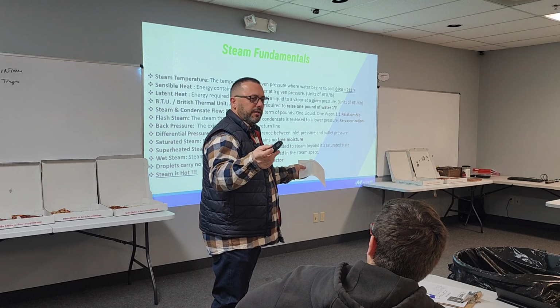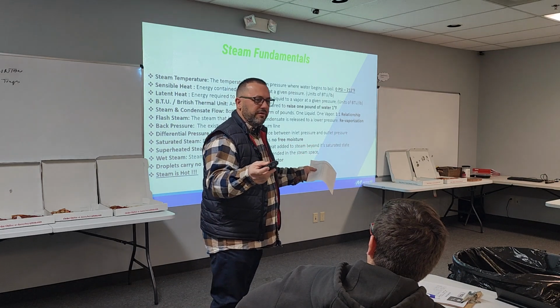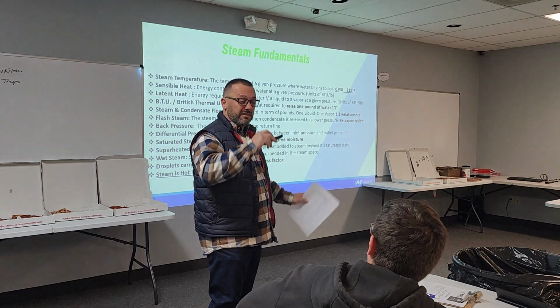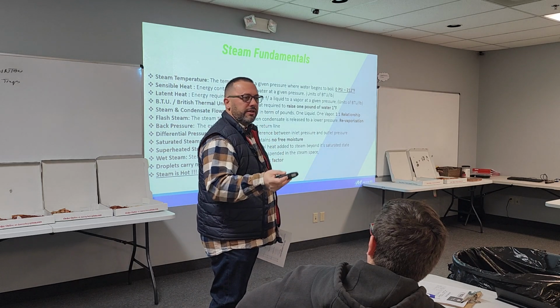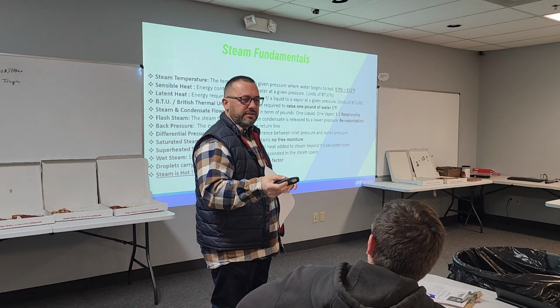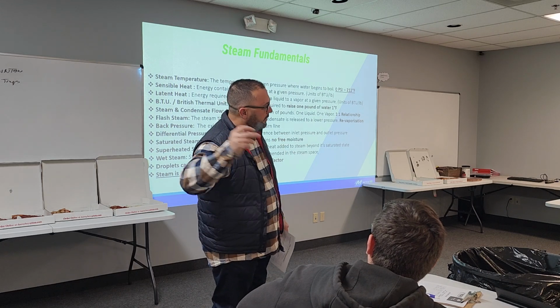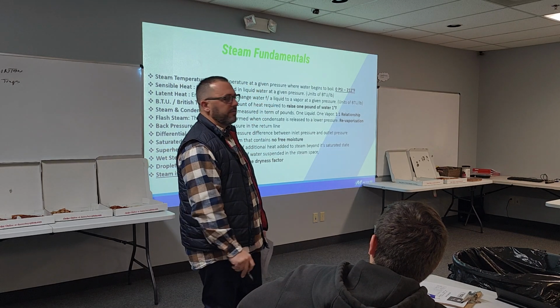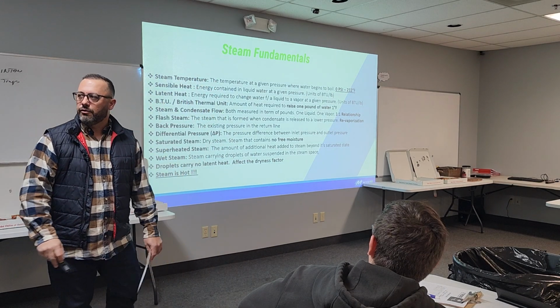That blows up to be 27 cubic feet, 1 pound of steam. In a perfect world in steam, if there were no leaks, after it gives up its latent heat, it would turn right back into that 16 ounces of water again, and we would hopefully return that right back to the DA or the feed water and reuse it all over.